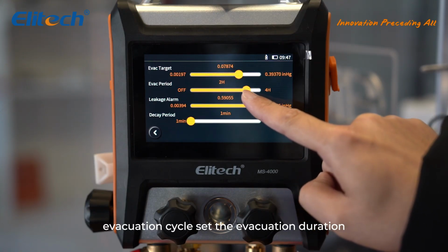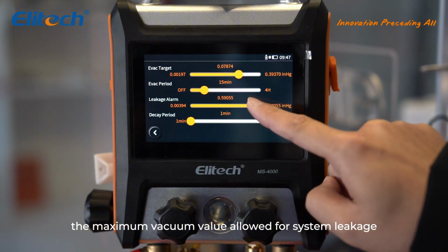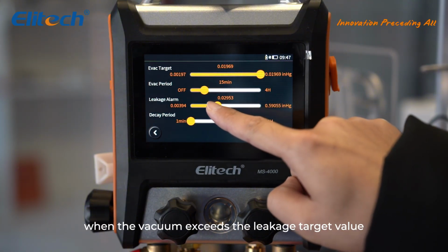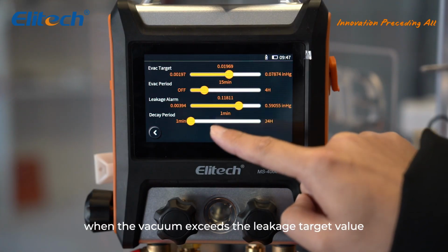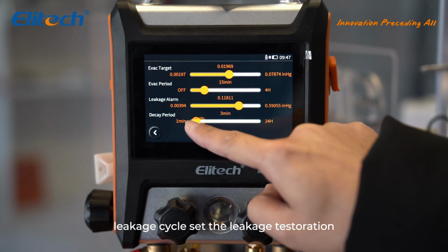Evacuation cycle: set the evacuation duration. Leakage target value: the maximum vacuum value allowed for system leakage. When the vacuum exceeds the leakage target value, the system test fails. Leakage cycle: set the leakage test duration.